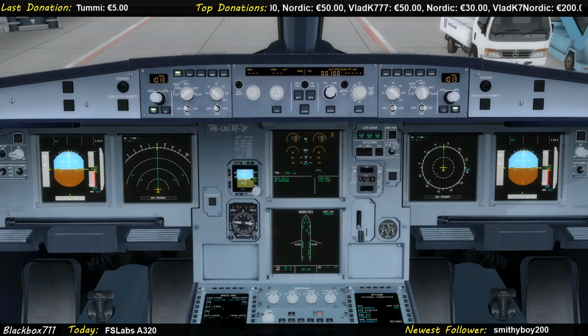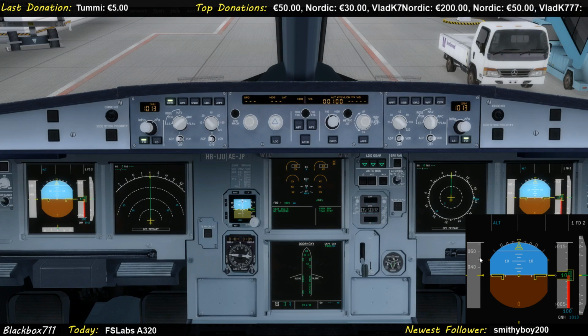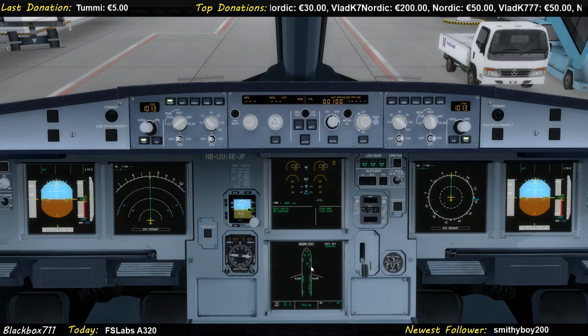And then you have two flight augmentation computers, FAC they're called. And there's two push buttons here, FAC1 and FAC2. They produce, for example, the characteristic speeds on the speed band. They will do the yaw dampening. So they are interacting with the flight guidance system or the flight control system. Also a very important part.